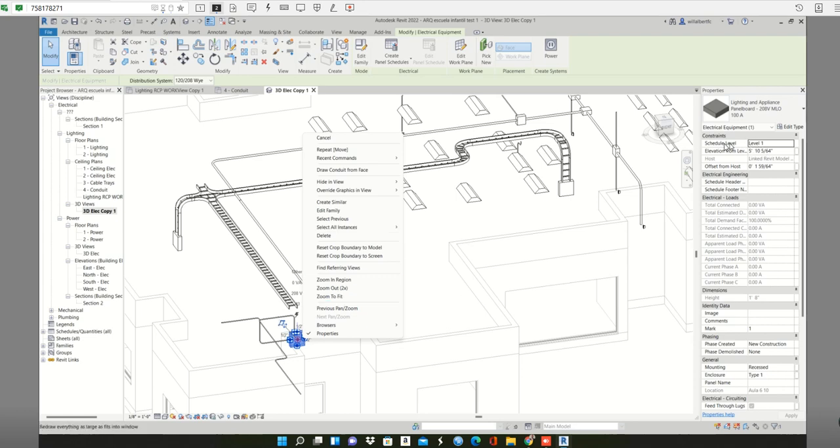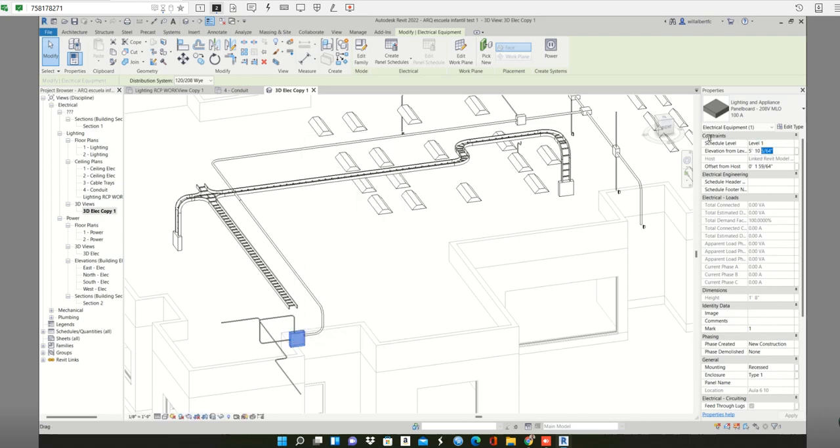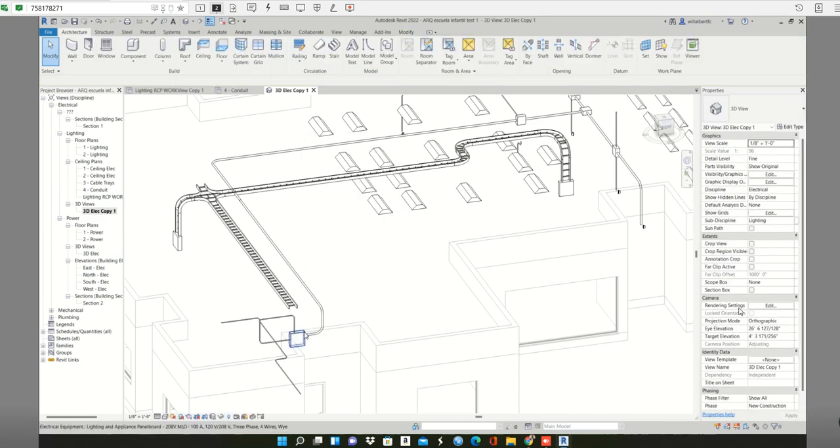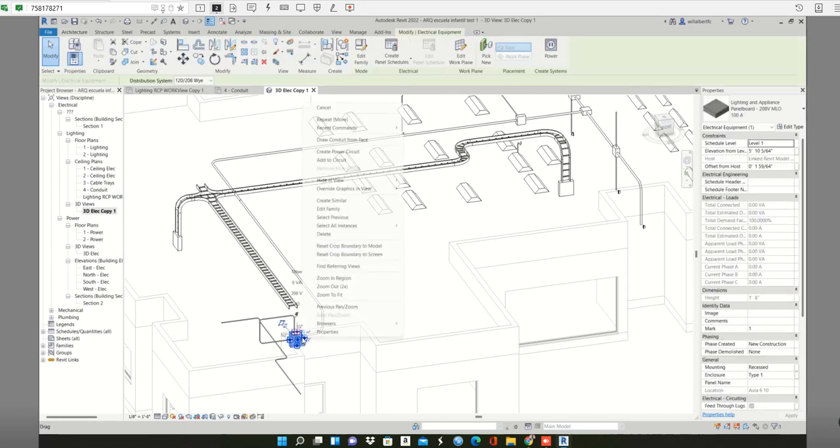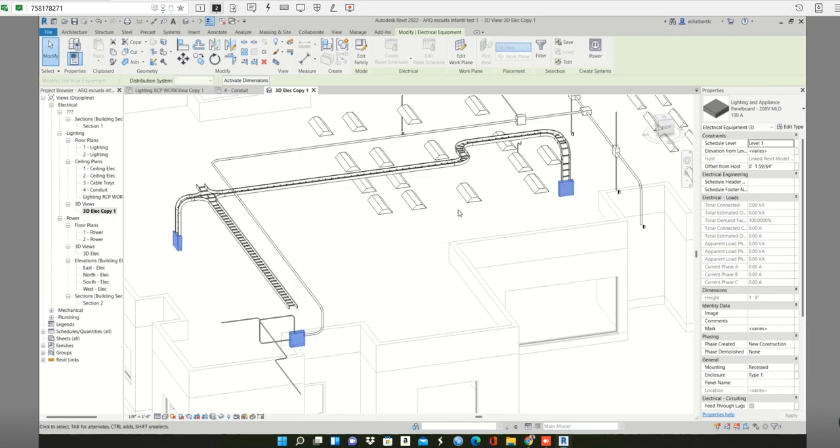This panel is associated to level 1, and from level 1 it has this elevation. So I'm going to copy. Yeah, 5 feet, 10 inch. Now select the panel, second click, select all instances visible in view, and in elevation you see that it says it varies. Now override that. You have the information on your clipboard, so just paste it. Control V and go to apply.